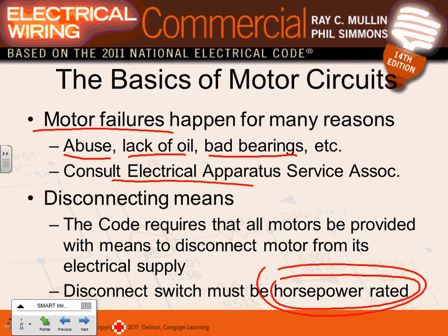amps, and you say 60 amp disconnect. Later on in the next project, in the industrial project, you guys are going to size it also based on horsepower. So if somebody accidentally flips this one down while the motor is running, it's not going to explode in your face. That's why they rate them based on horsepower. So it means you can interrupt the load.